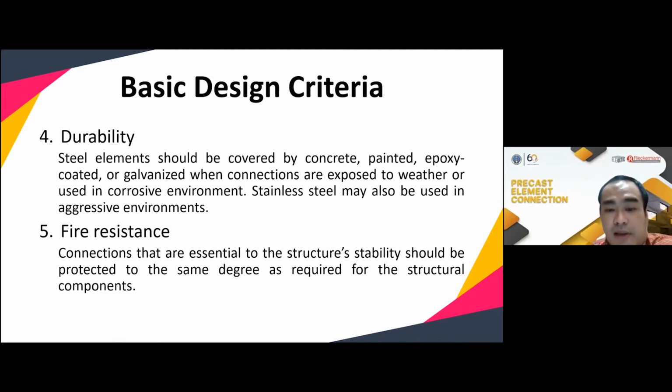And number 5 is fire resistance. The connections that are essential to structural stability should be protected to the same degree as required for the structural components. So we also have to provide for fire resistance.